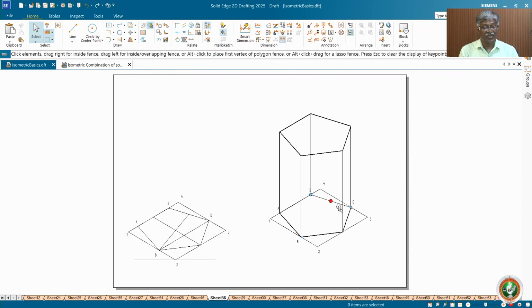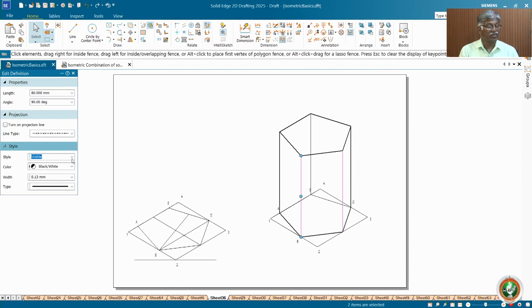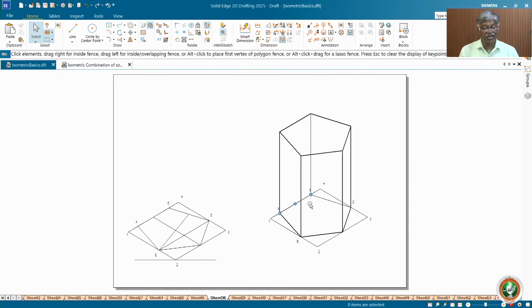Okay, the invisible surface, visible line. Yes, these two are dark lines, visible lines. Now the rest of the lines are not visible because AE, ED and also EE1 are not visible. So this is how we can complete the pentagonal prism.